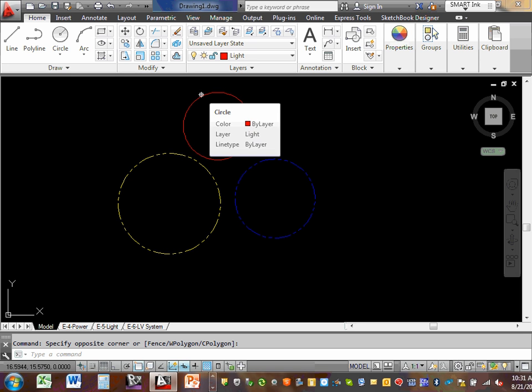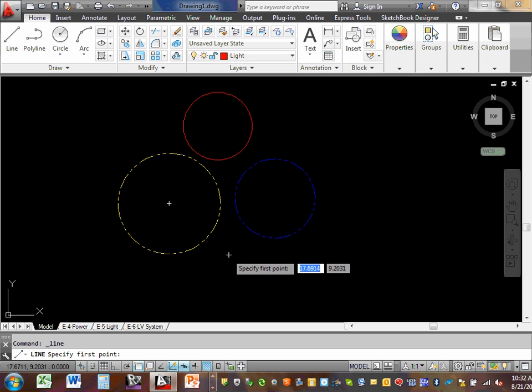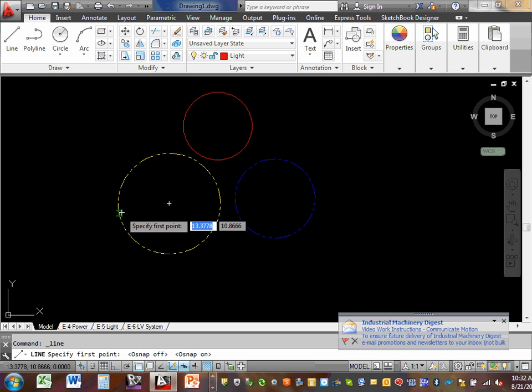Okay. Any comments, guys, about these? Yesterday I wanted to go over the trim because it's a very powerful concept. So I want you guys to go grab a line. Do you remember how to turn snap on or off? Click on snap object off. Can you guys see that? Snap object on. Click on that snap. So put your snap on and go snap anywhere.